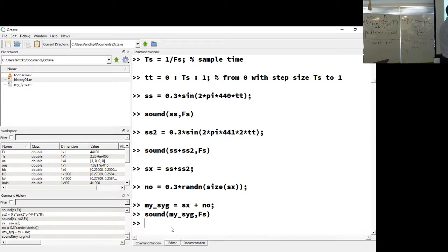The question is how the running average filter affects that sound. What do you expect? Running average actually reduces the high spectral noise, so it reduces the variation by the square root of the number of points. That's basically statistics. The linear time invariant system implementation in Octave is called filter.